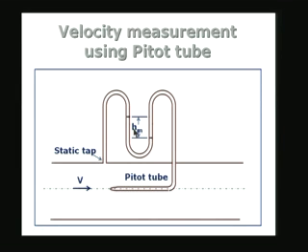So, this is a Pitot tube with a static tap on the wall of the tube, and the stagnation being shown by the hole, which is going to be connected to this. This tube is going to give you the stagnation pressure and static pressure here.